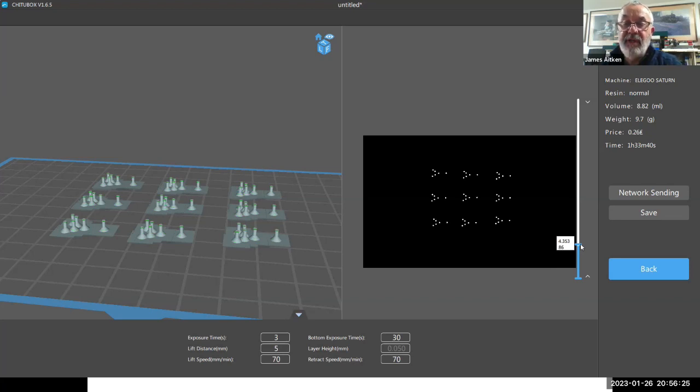However, as you will see in the photograph soon, it's upside down. So what you're looking at is, turn that upside down in your head, these are all hanging down from the build plate. And you can see the area here where you can see all the parts being, this is the slice, this is the amount of UV light that will come through the screen to actually harden the resin. And it's just these few dots. So these are our supports being made.